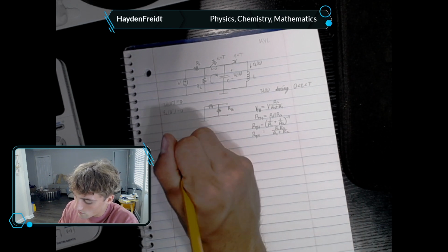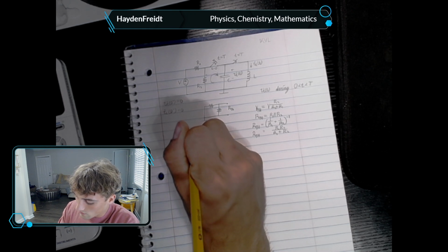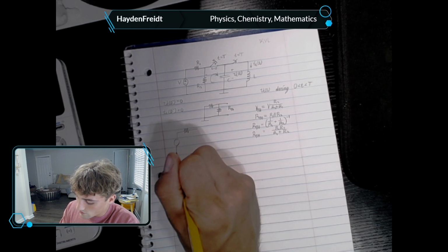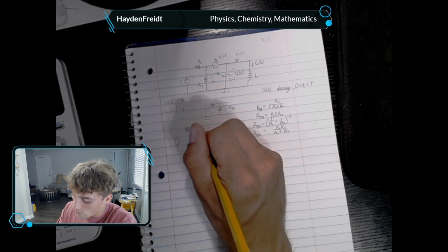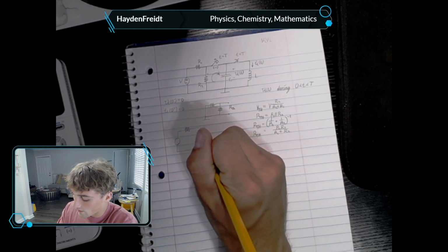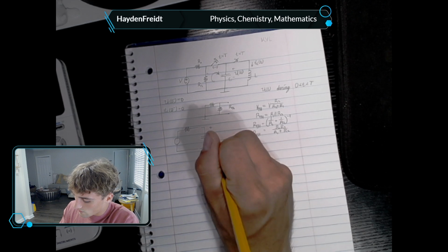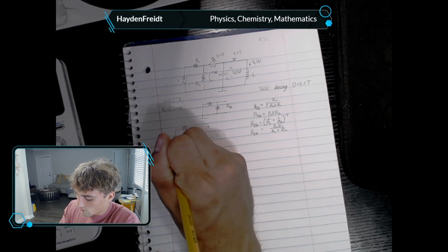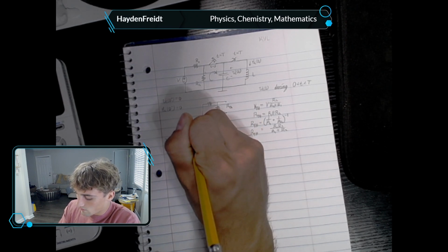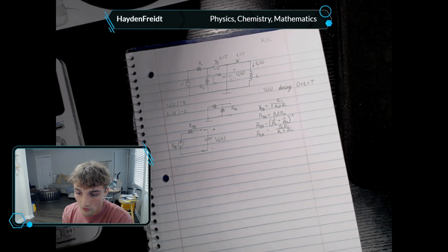Now let's draw our new circuit. It's just our simple RC circuit, which is what we wanted. The Thevenin equivalent circuit looks exactly like this: a source with a resistor in series, and then our output, our load, I guess we can consider it, is our capacitor. We just want to define the voltage across it, Vc of T. Positive, negative, this is V Thevenin, and this is R Thevenin. Just like writing our first order linear differential equation, this is going to require the capacitor's constitutive law.